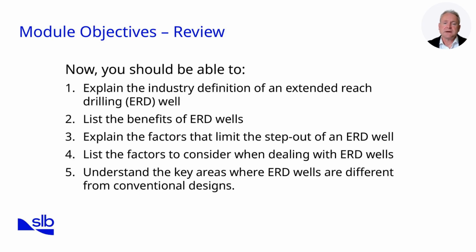We discussed surveying and geological uncertainty, where even small errors become amplified over long displacements, requiring advanced survey techniques and improved practices. We also analysed torque, drag, and buckling, and the need for realistic modelling and operational controls. Finally, we covered BHA and drill string design, showing how hole cleaning, tool durability, and stability matter more than maximising penetration rates. Together, these topics give you a comprehensive view of ERD well design considerations.